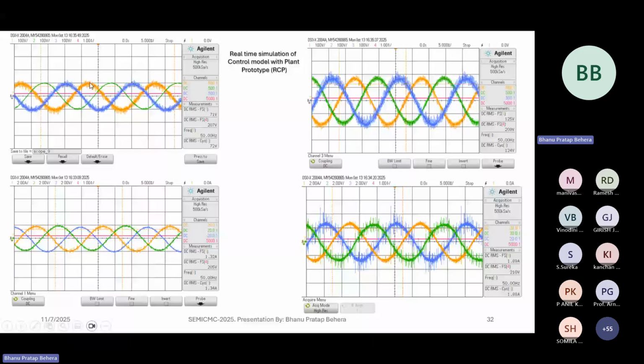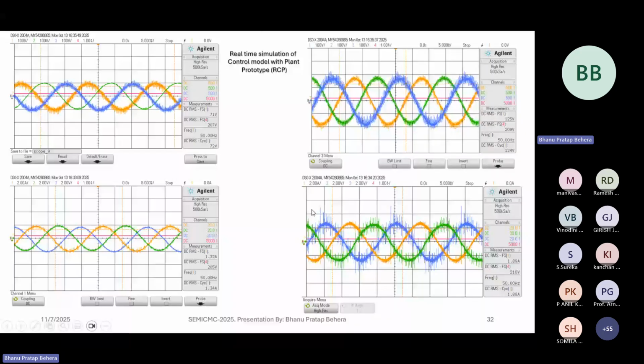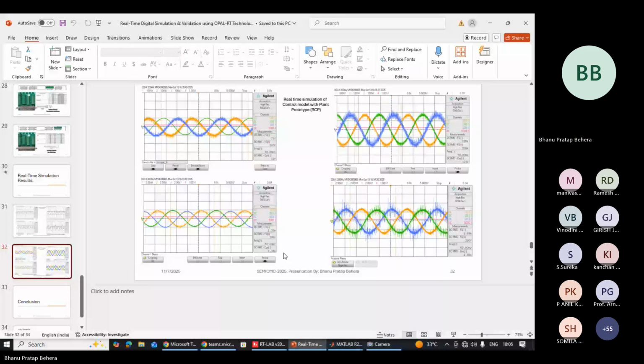the communication, because whatever wire we are using from the sensor out to the analog out is not a coaxial cable or twisted pair cable, due to which this noise comes into the sensor module. So through open loop we have tested and validated, then accordingly we will change the wire, and then we can go for the closed loop. So this is all about the real-time simulation.